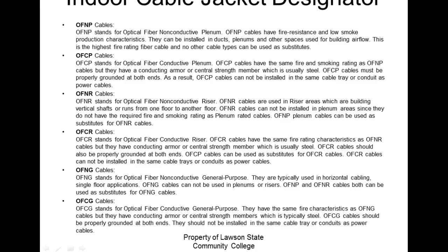So OFNR. So what can we use of this? It stands for optical fiber non-conductive riser. OFNR cables are used in riser areas, which are building shafts. So when we talk about a riser cable, that means this cable has the ability to run vertically. If it's not a riser cable, it means that cable can only run horizontally, right? Does that make sense? Okay. So that means this is a riser cable, so we can use it in vertical shafts that run from one floor to the other.